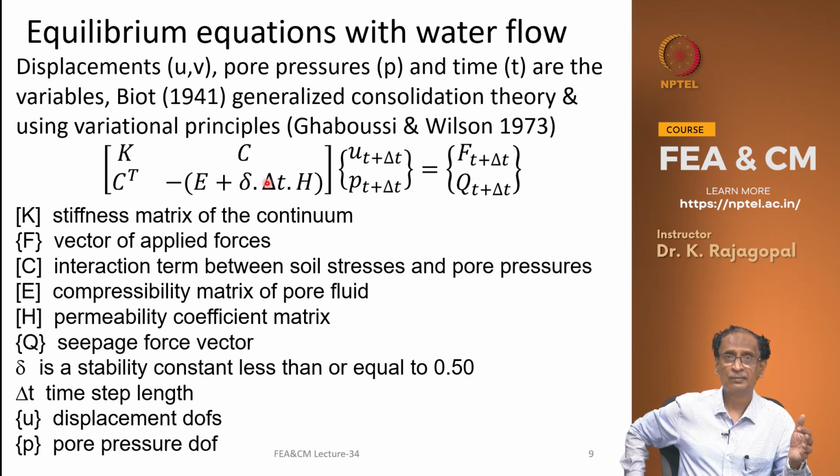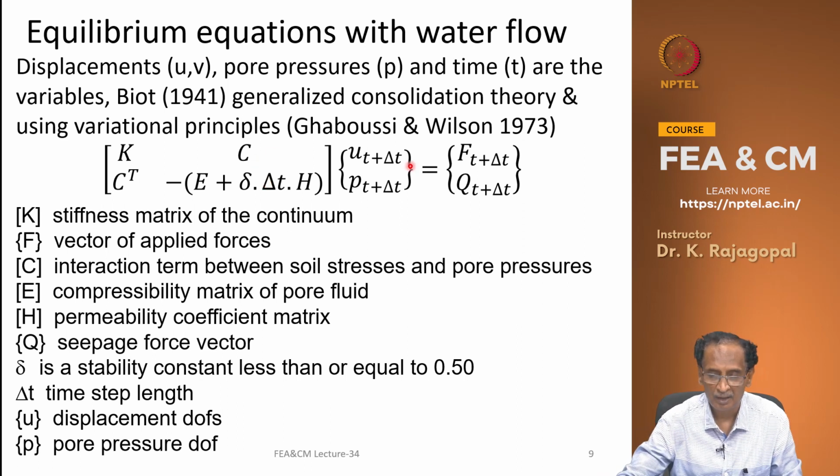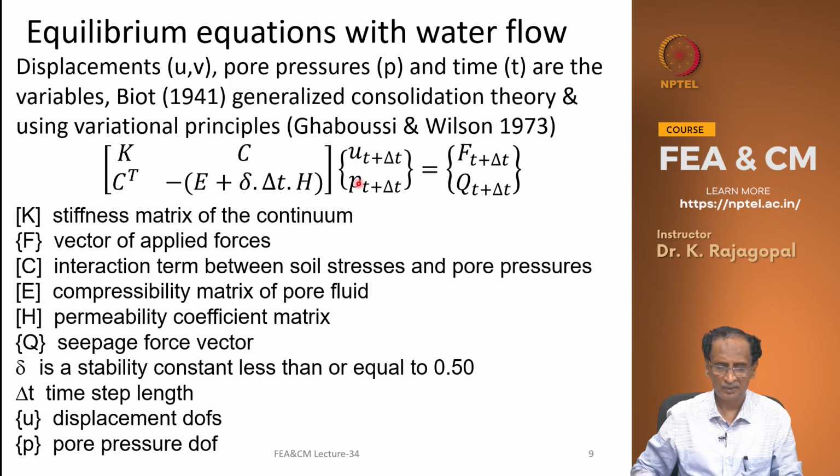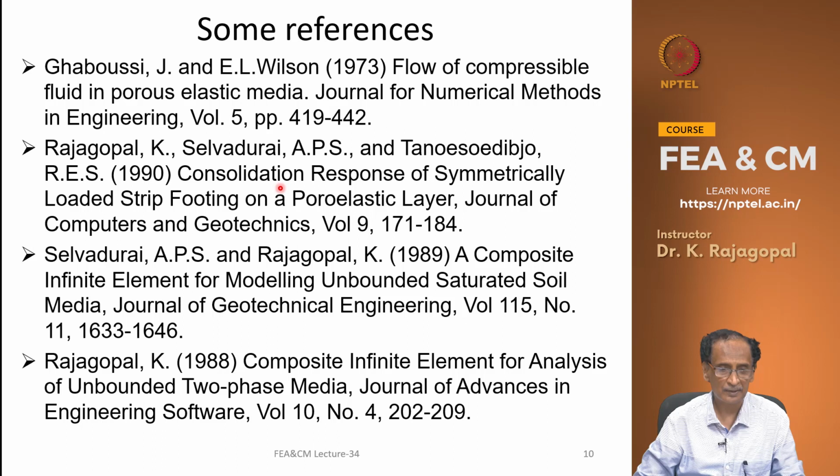We can give any variation that you want, and by solving this we can get our displacements and the pore pressures. So actually it's a very time consuming process, because the stability depends on the delta t, and so we have to do a time stepping process to get the solution for the next time steps.